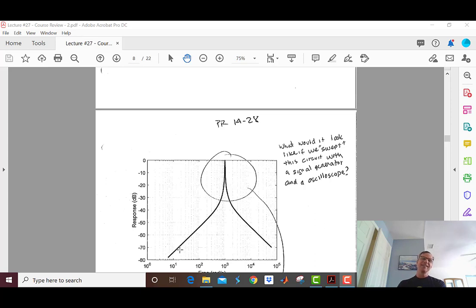Down here, the capacitor is blocking or limiting the current because the capacitor has higher impedance at lower frequencies. Here, the inductor is limiting the current. So this gives you a really good feel for a resonant circuit. What's really happening? The capacitor's limiting the current, so the current is low. Nothing's limiting the current but the resistor. Here, the inductor's limiting the current.